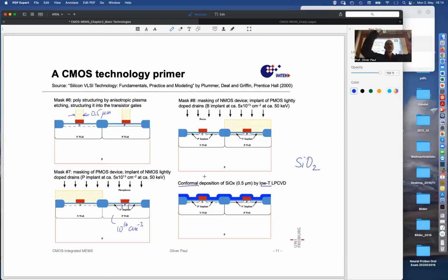If you have an anisotropic process, let's say where you do a physical evaporation from a source, molecules or atoms arrive, and they arrive in a directional way, and then they get deposited where they can be deposited. And if you have some step, there's no reason for those atoms to go around the corner and cover the sides of those steps. That would not be conformal.